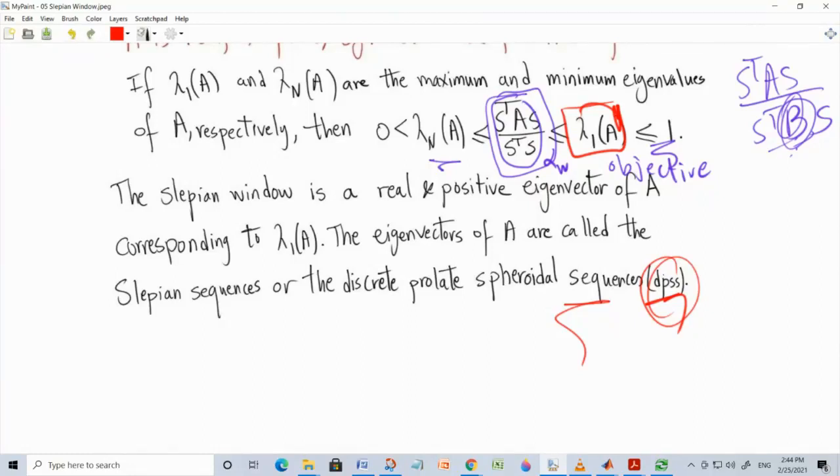We are not done yet in terms of making the DTFT practical. For the DFT to be practical, you have the windowing business, where the most important thing is to have a finite sum, but we still have a problem, which is that the DTFT has a continuous frequency variable. We cannot deal with an infinite number of frequencies. We need to deal with the spectrum computed at a discrete set of frequencies. And so this will be the last step to go from DTFT to DFT. We will have to sample or discretize the frequency variable.